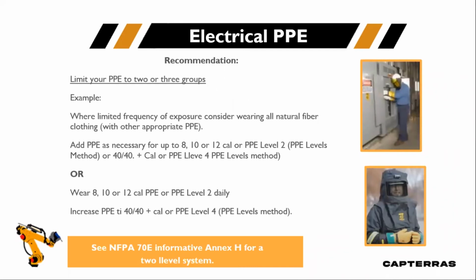Electrical PPE, or personal protective equipment. Recommendation: limit your PPE to 2 or 3 groups. For example, where you limit frequency of exposure, consider wearing all natural fiber clothing with other appropriate PPE. We need to choose our PPE depending on the risk level.